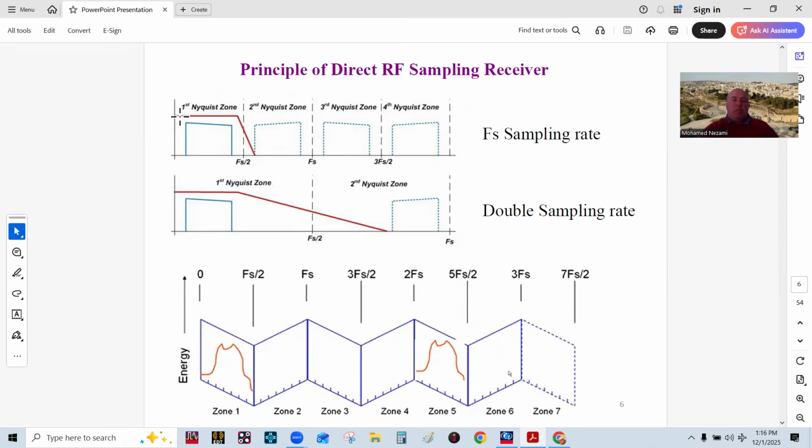Now, a lot of times, of course, you have to make sure, because of the nature of the digitized signal. What happens when you digitize a signal is that you really convolve a baseband signal with a pulse, which is sampling. And from basic linear system classes, when you convolve an impulse with a passband signal, you basically get a repetition.